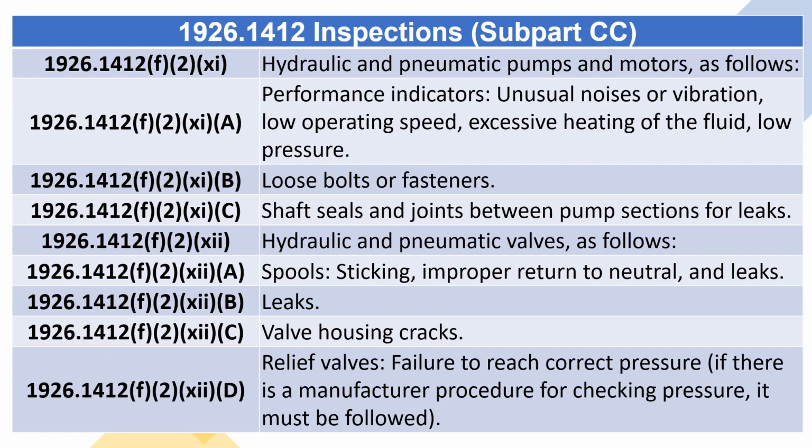Hydraulic and pneumatic pumps and motors, as follows. Performance indicators: unusual noises or vibration, low operating speed, excessive heating of the fluid, low pressure. Loose bolts or fasteners. Shaft seals and joints between pump sections for leaks.